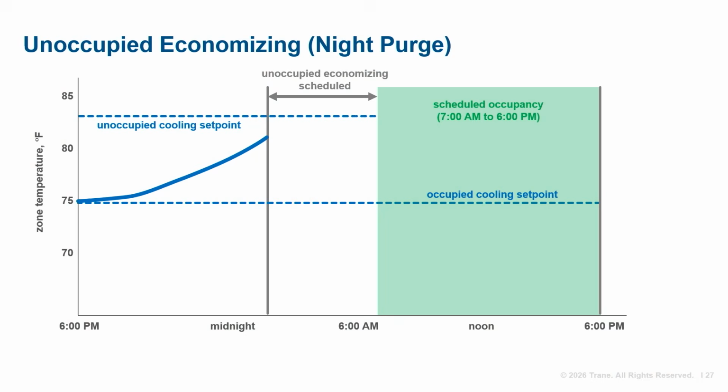This strategy further saves energy by allowing indoor temperatures to begin drifting early. Both optimal start and stop strategies can be used for cooling and heating. During the unoccupied mode, the indoor temperature can sometimes drift up, which is warmer than the occupied cooling set point. This requires the system to enter a morning cool down mode prior to occupancy.